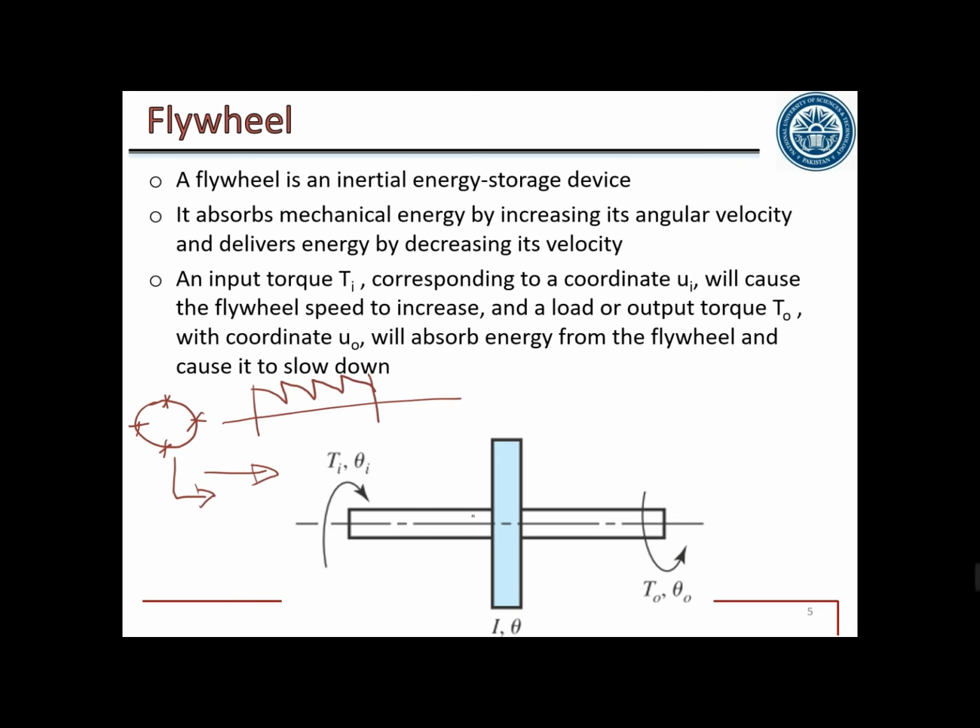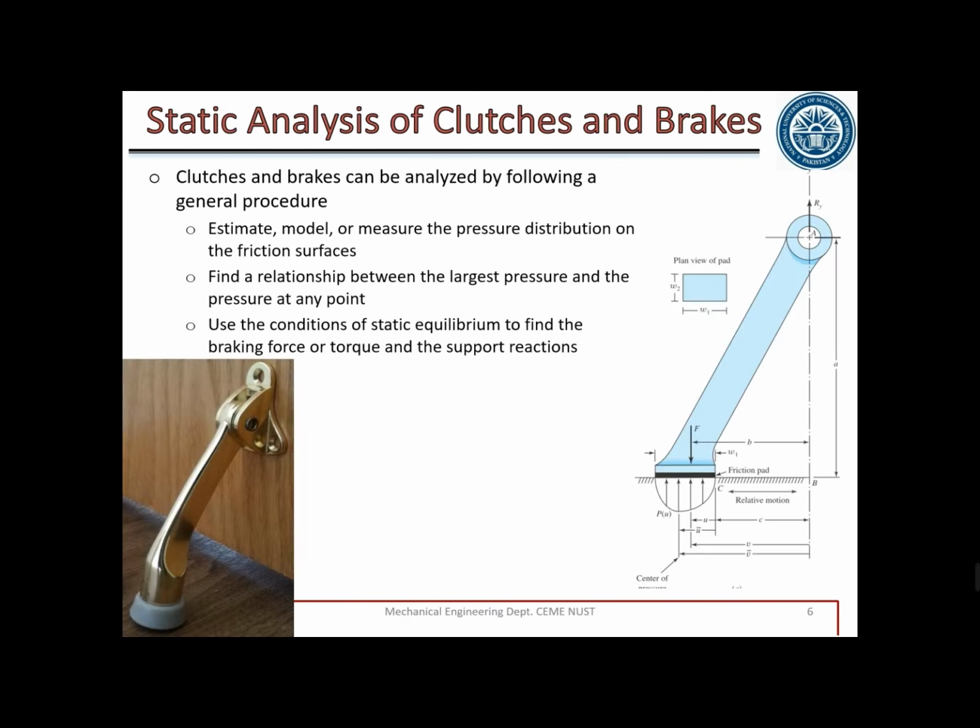So what the flywheel does is store this discontinuous energy, and it provides a constant output omega. It stores the energy from the engine, and it provides energy in terms of T and theta, in terms of omega, as output power to the car wheel. So that is the function of the flywheel. It stores the energy from the input source, and it provides the energy to the output.